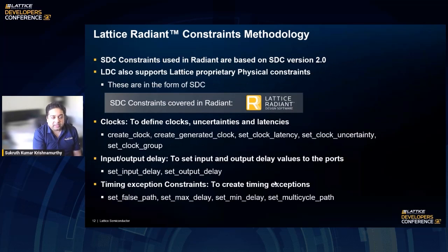As mentioned, the SDC constraints can be used by both LSE and Synplify Pro, and in Radiant, the SDC constraints used are based on SDC version 2.0. LDC, which is the Lattice proprietary constraints file, is supported by the Lattice Synthesis Engine and also supports some other physical constraints. These physical constraints are also in the form of an SDC file.